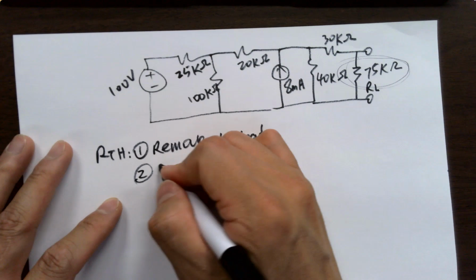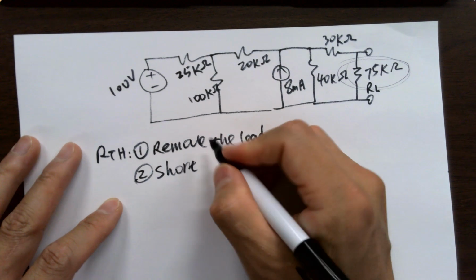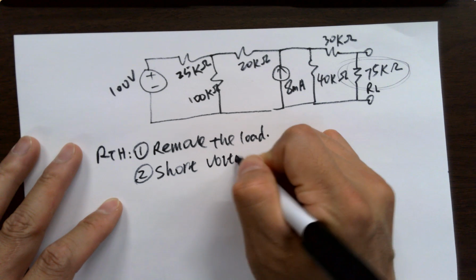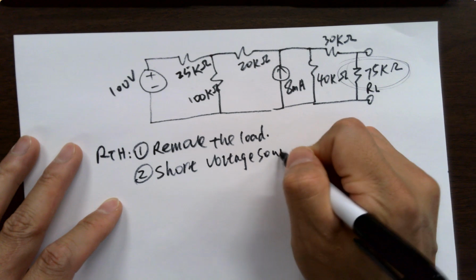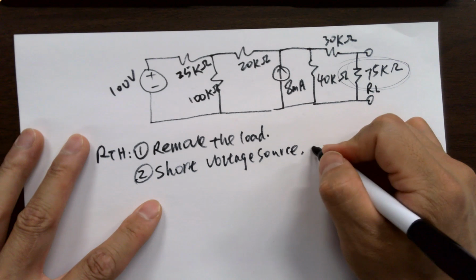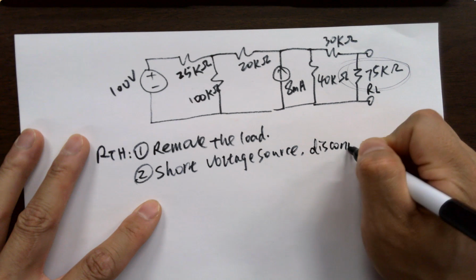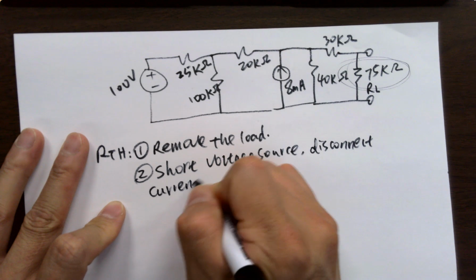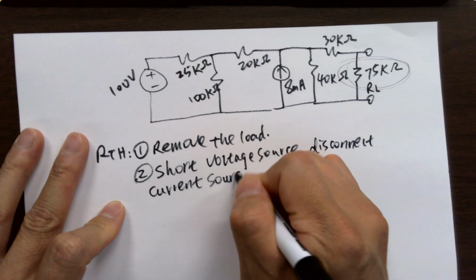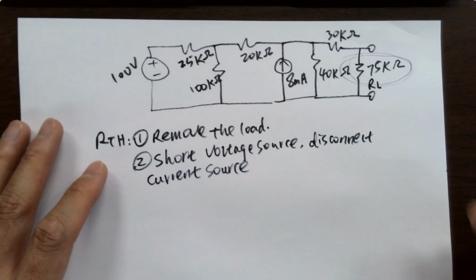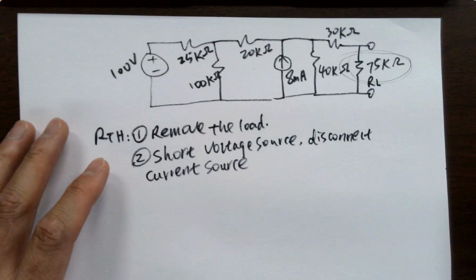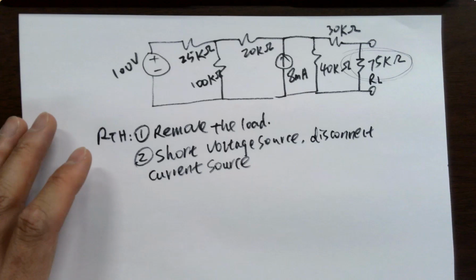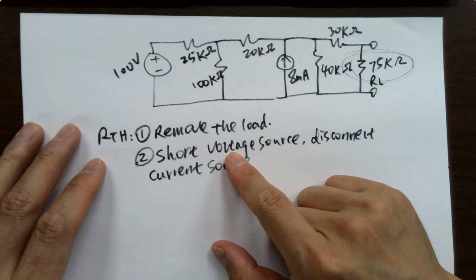Second, short the voltage source and disconnect the current source. This could be the first challenge for you guys. Always get confused why we have to do that.